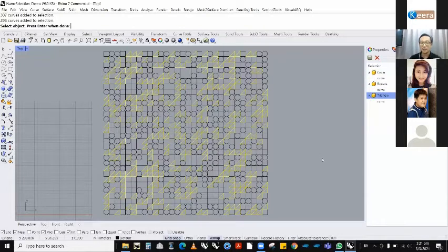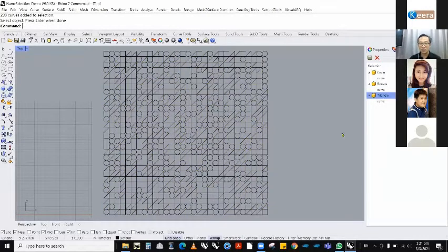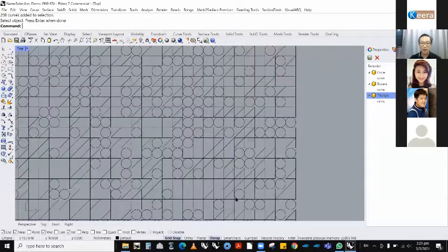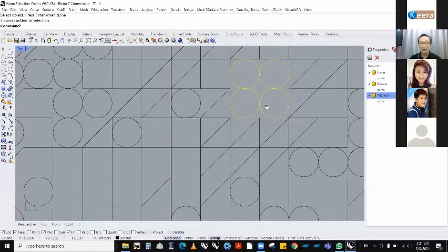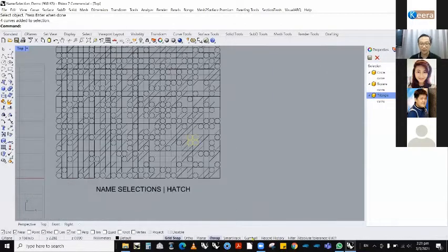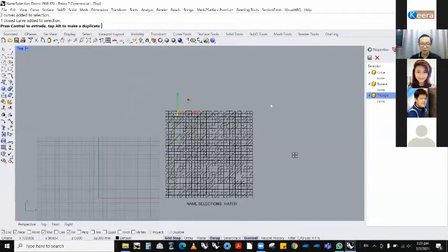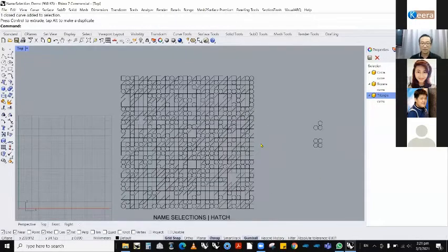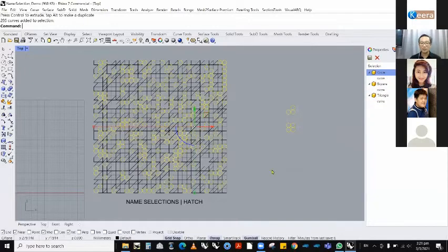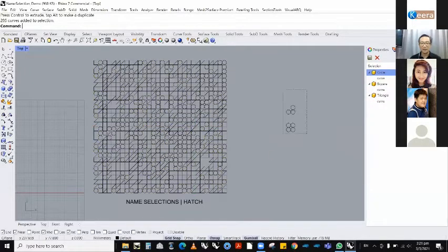The nice thing about this is it is not grouped. Let me explain this now. Once I am able to do this, I can manipulate this. If I'm in a group, I will not be able to do this. If you use Rhino long enough, you understand that if you pick on group items, everyone else will be selected and you can't move this out. If I pick on circle, the circles are still intact. So if I delete, the circle, let me just undo this.